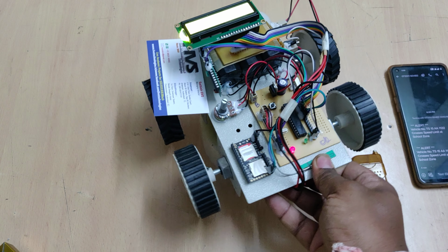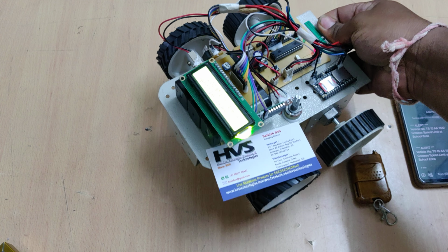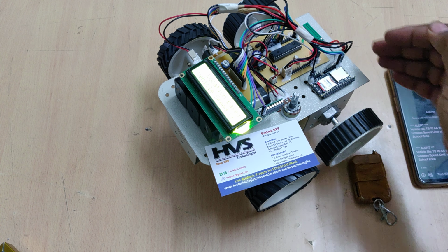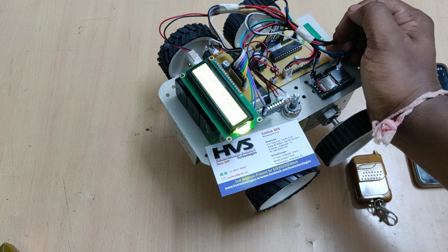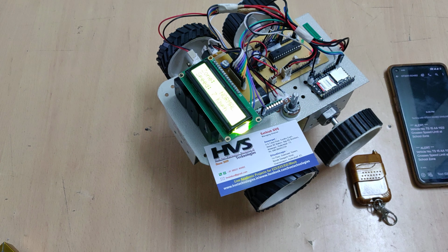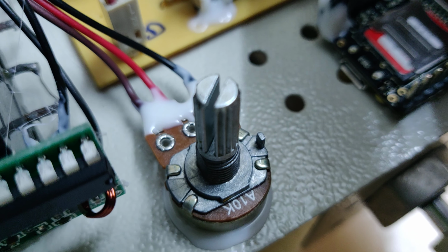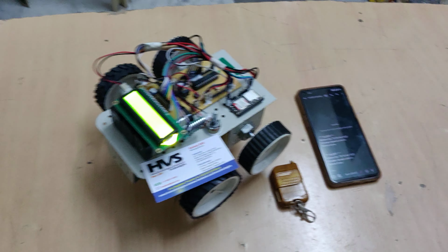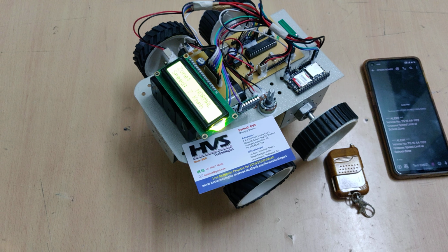Wait till the SIM card gets the signal. That will be confirmed by calling the SIM card, or else one blue light will blink. I'll show you, it will blink once it gets the signal from the subscriber. You can see that one light is blinking under the GSM modem. So there is a blinking confirmation from the GSM modem. For double confirmation, you can call it.